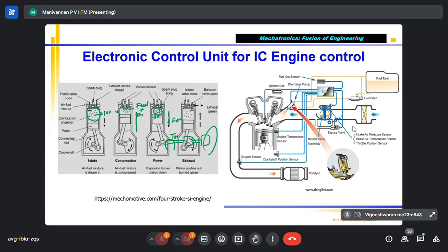Now that compression has ended, the piston has come to the TDC position. Now if you give a spark, fuel will burn. But we know the crank is still continuously rotating, so the piston will start coming down, because it is not going to remain at TDC. Now if fuel burns, high pressure is created, but the piston is already moving downward. The volume is expanding. Even if the pressure increases, not all the pressure is converted into force. Why?